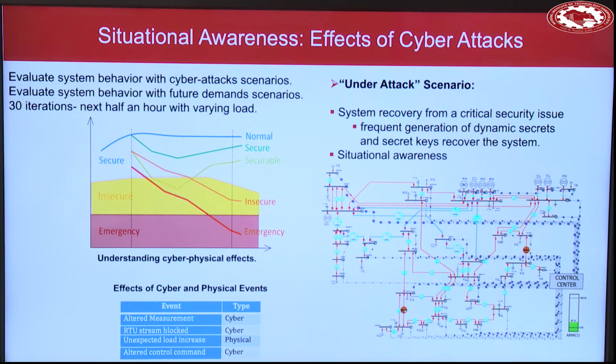Now this is how it looks. Sitting at the control center, from the substation you're collecting data. Now we model this, in a way that could help operators. The blue lines, the blue dots, right? These blue dots are communication. They are packets that are being sent from RTU to control center. If the size is larger, that means the payload is large and the packet contains more bytes. If the size is small, through that you also define it.